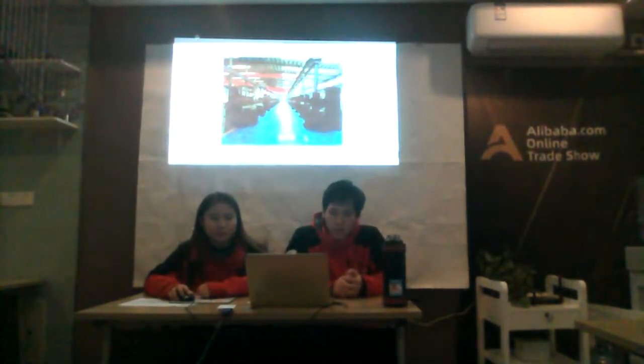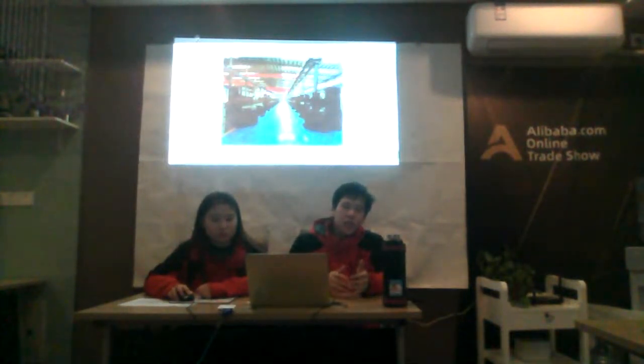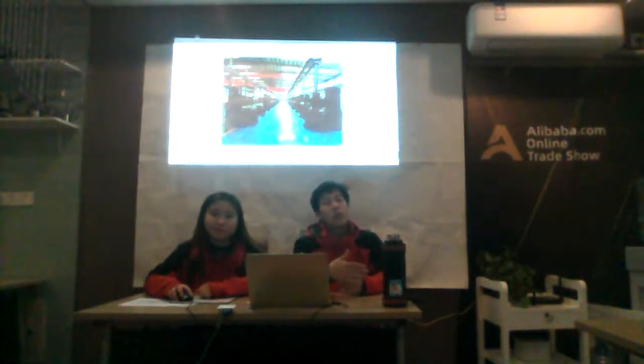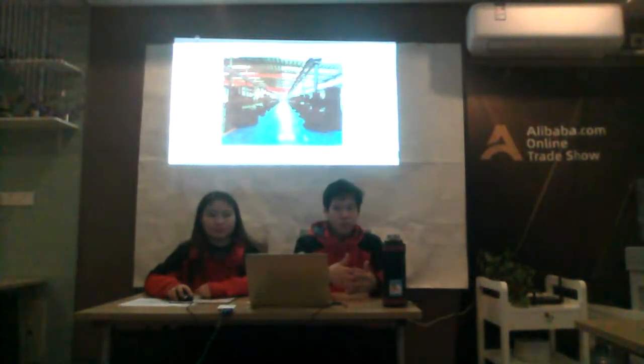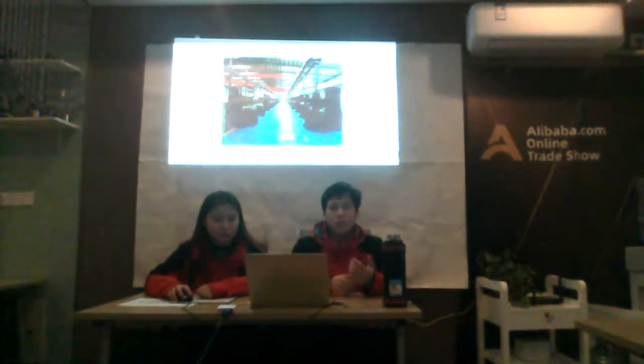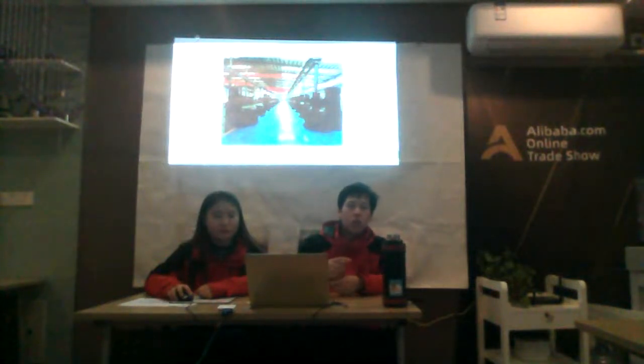We have a special engineer to do the maintenance work on the machines to make sure the machine components stay in very good condition when the customer comes to visit. They will test all the machines, as these are the 5 main parts, and they will do the inspection and accuracy test to see that the work table rotates very smoothly and in the same direction when it does the circle stroke around the spindle.